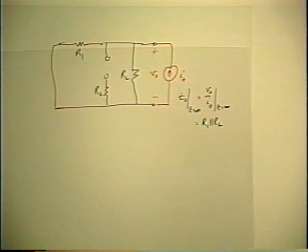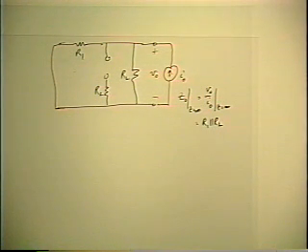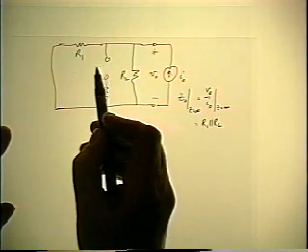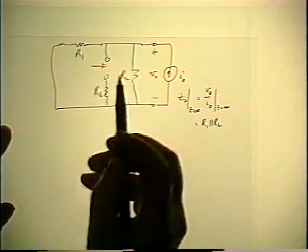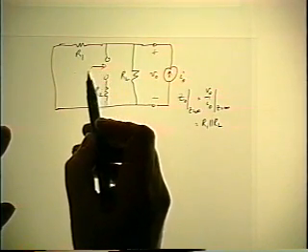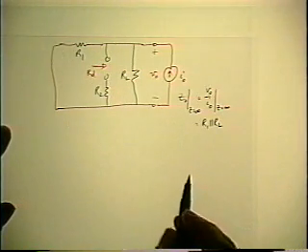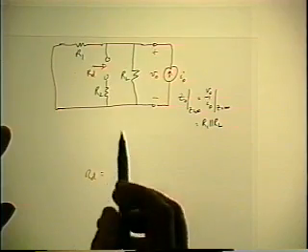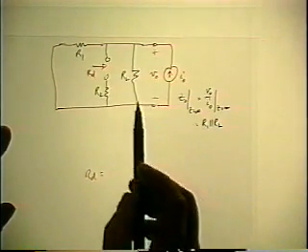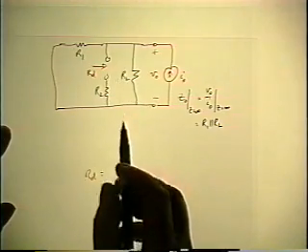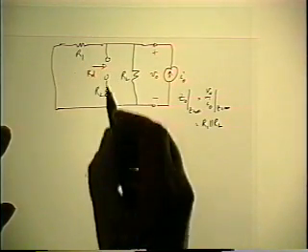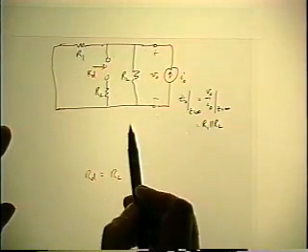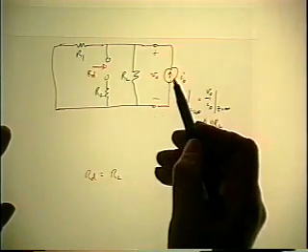Now we have to calculate two driving point resistances. So first we look in where the element is going to go, and we want to calculate RD. So RD is single injection, calculated as the resistance looking in, which is R2 to ground in this direction, and in the other direction R1 parallel RL, because the input is going to be 0.